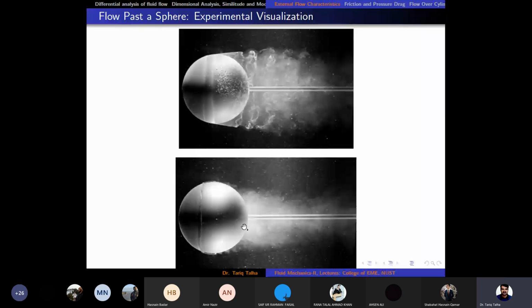So that is basically the entire phenomenon of reverse swing, that we make one side shiny so that the boundary layer would remain laminar, and it separates at theta equal to 80 degrees, while the other side, which is rough, the boundary layer becomes turbulent and it remains attached. So that's why the flow separation happens at theta equal to 140 degrees.